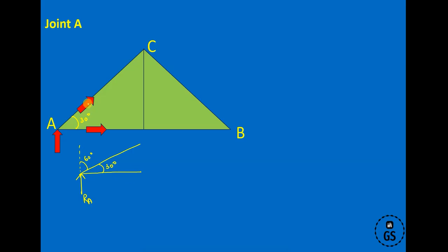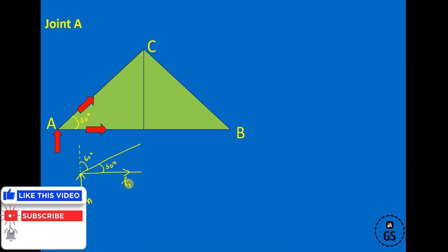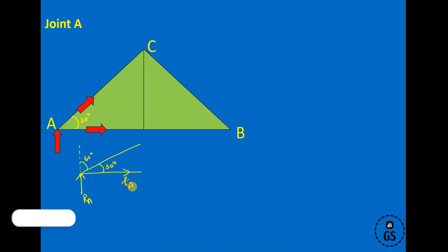Initially we don't know the nature of the force, so what we do is assume all the forces outward. Now KAB, and over here KAC. What is K? K is nothing but the virtual force which we are assuming, at 1 kilonewton, right? Now resolve these forces. Let's apply vertical reactions. In this case the vertical reaction is RA, plus KAC cos 60 degrees equal to 0.